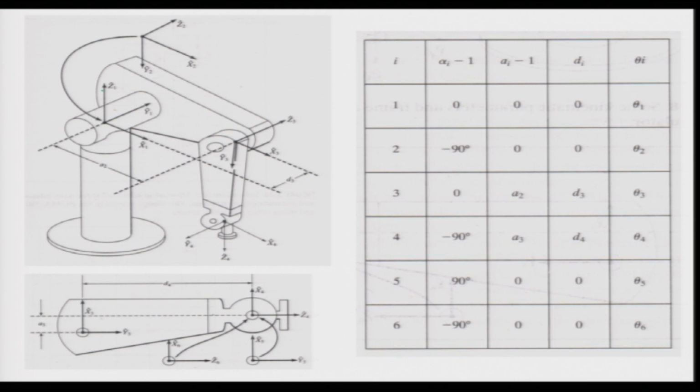So let us start off by understanding the working of this first. So first there is a 0 axis here. So 0 and 1 axis can rotate about this, that is my 0 and 1. The first axis is along this, 0 and 1 we can take it. So this is my waist axis. So let us assign 0 there and 1 there. So it can rotate like this about the waist axis, which is here, the vertical axis. The second axis is the shoulder axis, which is this one. So this is my shoulder axis, which we can call Z2. The third is an elbow axis, which is Z3 here, okay, and this part is shown here, okay, for clarity.